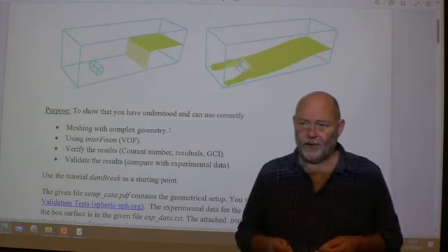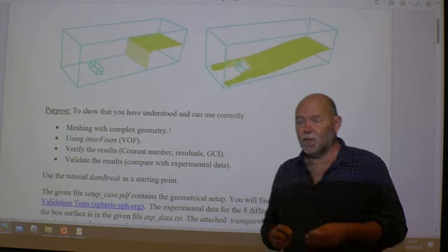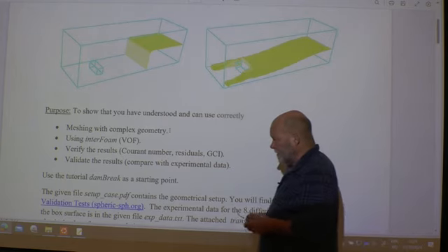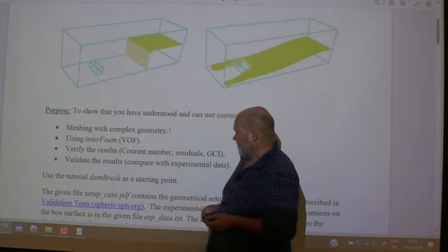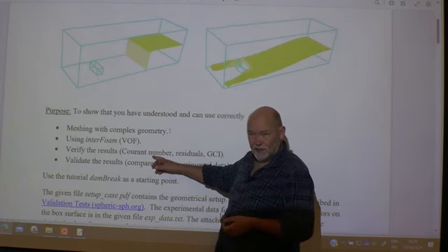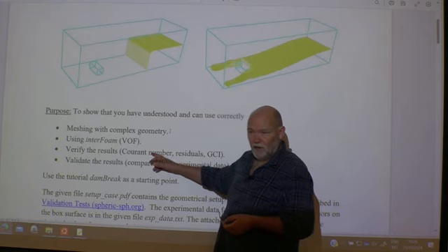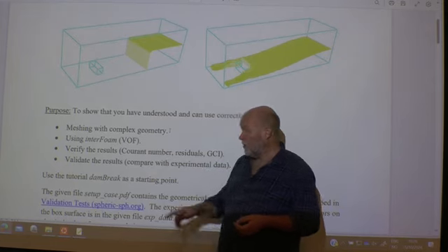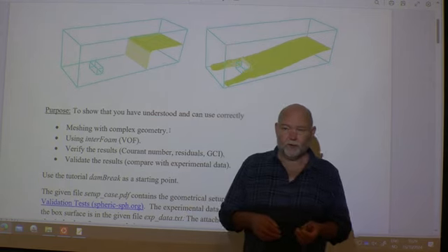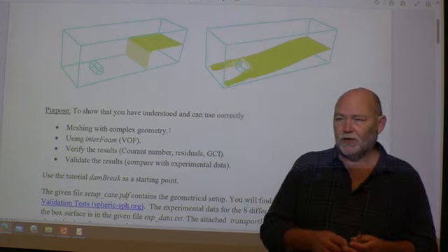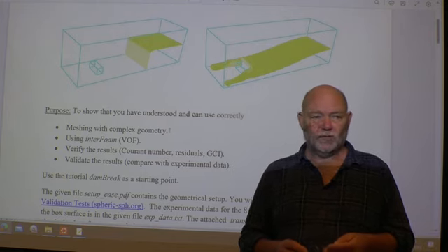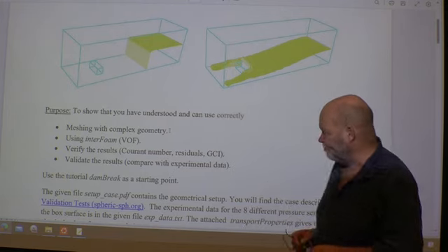Maybe you should have a second order time scheme there, Crank-Nicolson or something like that. And also keep the Courant number low. For implicit schemes, yeah, you can have a Courant number of 2, 3, 4, 5. Don't do it. It should be 1 or smaller, clearly.